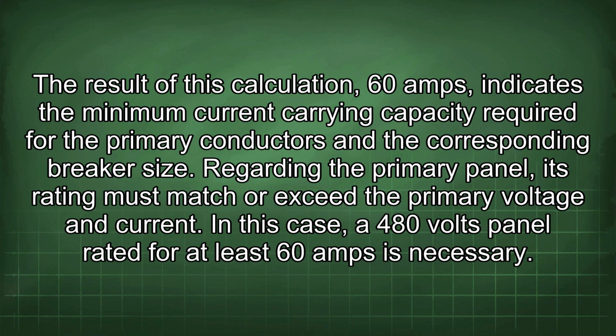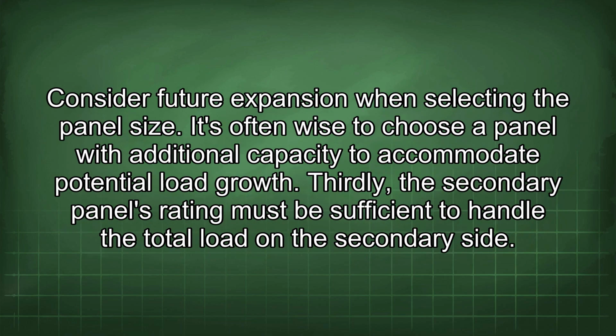In this case, a 480 volts panel rated for at least 60 amps is necessary. Consider future expansion when selecting the panel size. It's often wise to choose a panel with additional capacity to accommodate potential load growth.